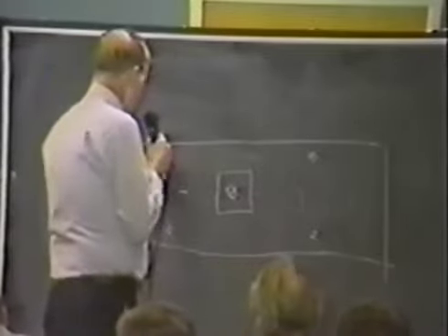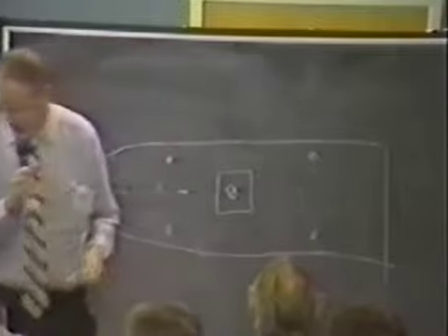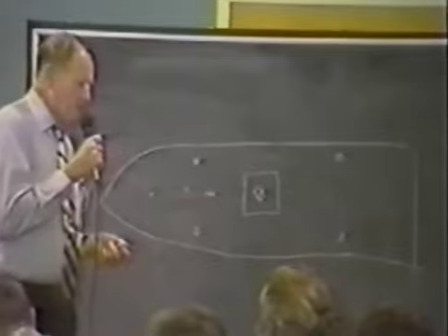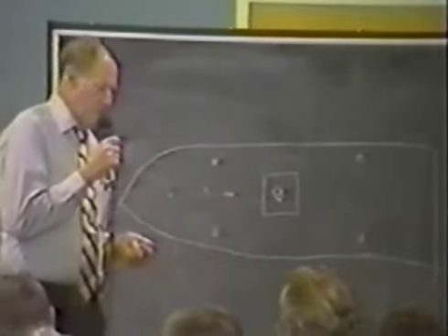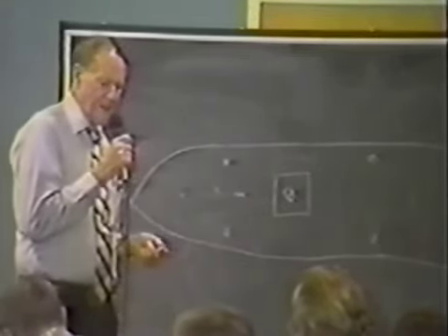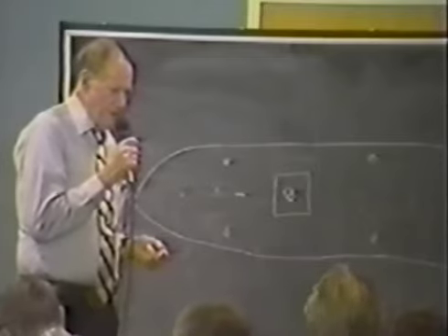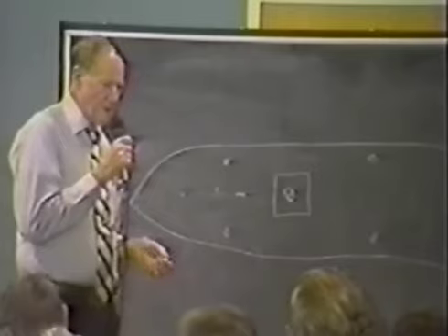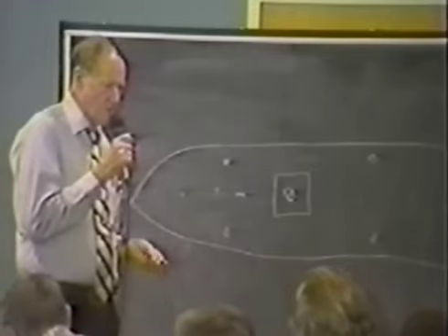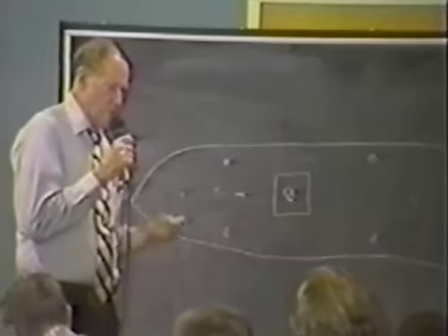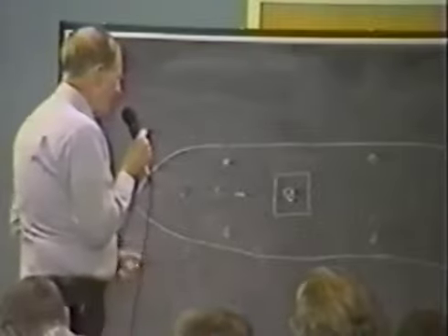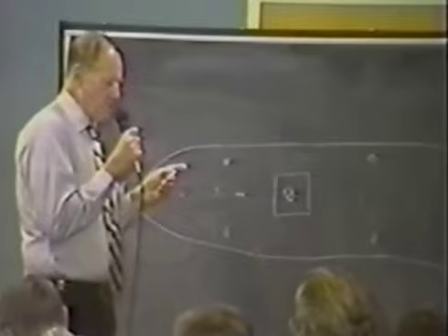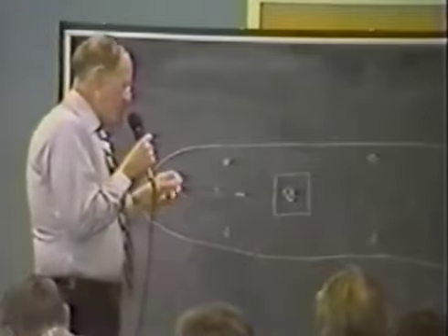The magnetic system consisted of 2 huge generators, 275 kVA generators, electronically locked to each other. For reasons which I don't recall now, each had 5 field windings. There were 10 total. Each field winding was driven by a bank of 300 6L6 tubes, so there were 3,000 total. There were buffer drivers for those and so forth. They had to be able to modulate, turn on and turn off the current in the 5 windings, and they did it in a manner such that